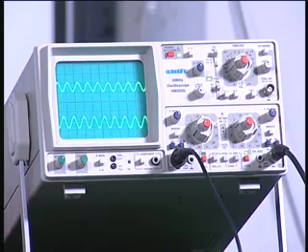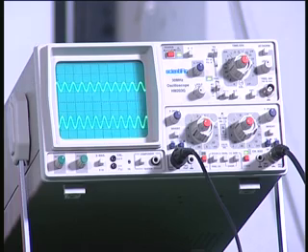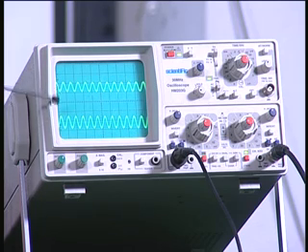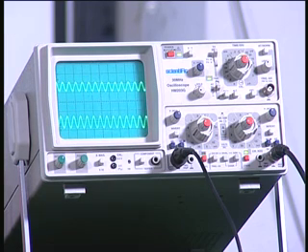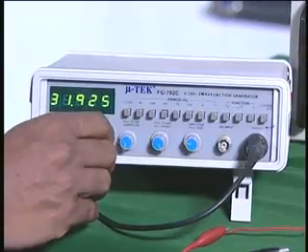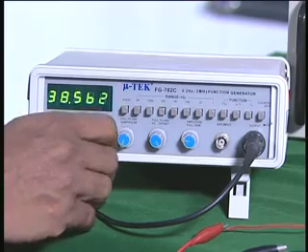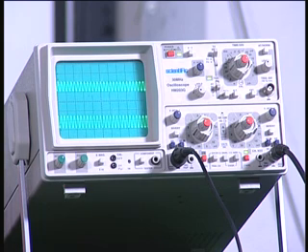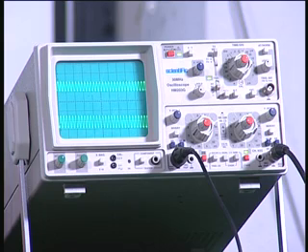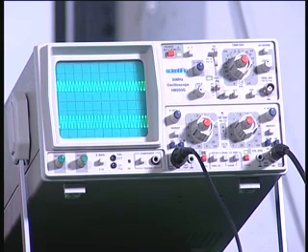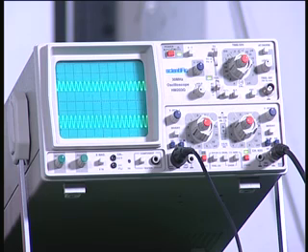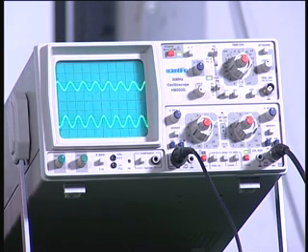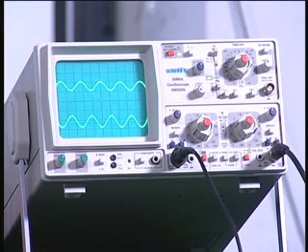You see when I keep increasing, you can see the frequency increasing, but the amplitude of the output is almost constant. The amplitude of the output is constant, both the input and the output, till I complete the entire range of frequencies using this knob. Now I have almost come to the end of this, and the frequency also has increased. Now I will go to the next multiplier. So I will bring it down to the original value and go to the next level of frequency, which is now in 10k.